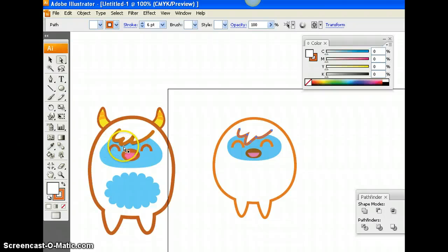Now then, to get that effect there, that kind of shadow effect, Control C to copy that shape, and then Control B, B for behind, to paste it behind this original shape. So Control C and then Control B. And I promise you there is another shape there. There it is. Okay? For that one, we're going to make the fill color black.